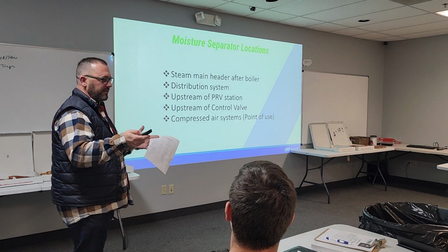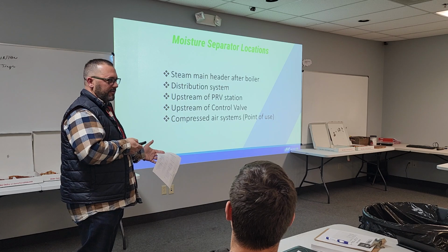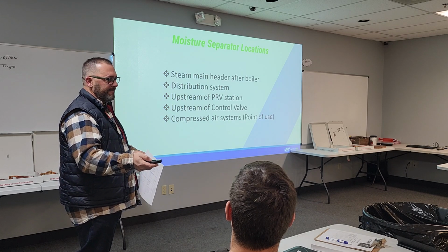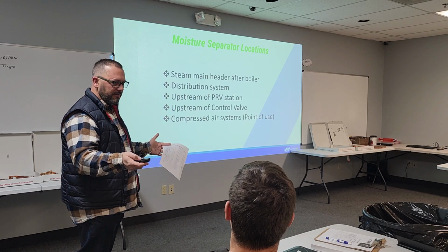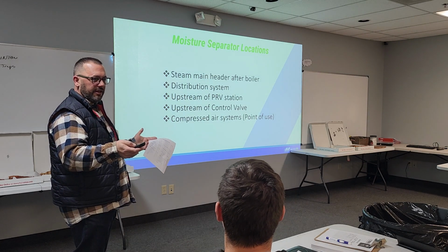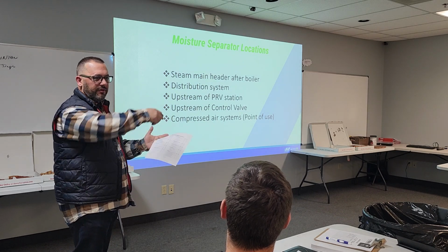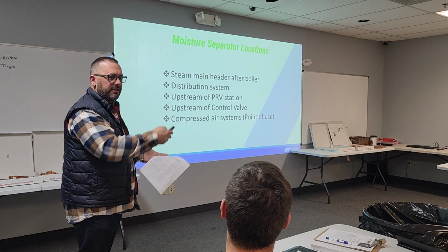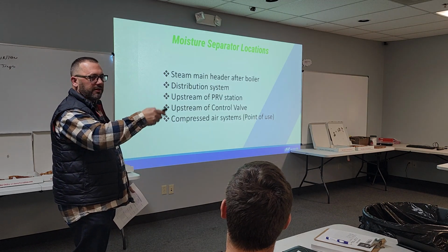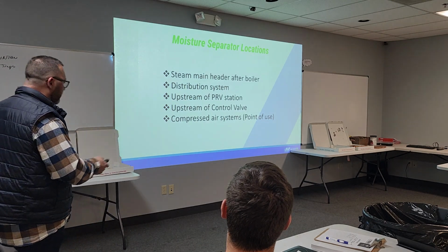Good piping practice on the steam trap says that you're going to stick a strainer before the trap and a check valve after the trap. That's a 20 to 40 mesh strainer. I don't care how you install that. But when you're installing a 4-inch flanged strainer in front of a PRV, you don't have it hanging down. You put it on its side, because otherwise it's like a 5-gallon bucket of water, and all that happens is it gets picked up and flung and hits that control valve, and that's what kills everything quickly.